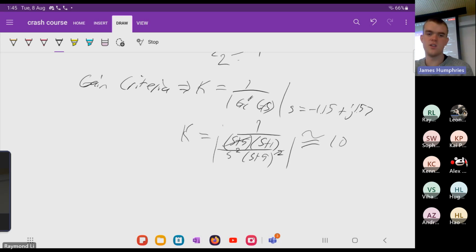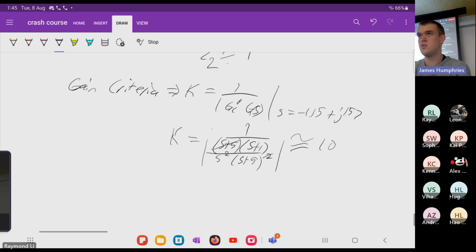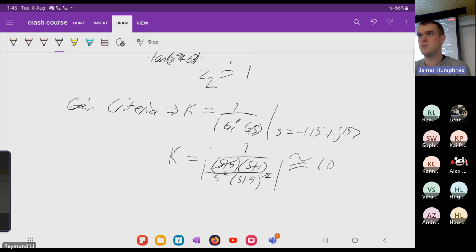Okay, perfect. So you chose where to place the 0 just to cancel the whole, right? Yes. And then the other 0 you chose with the angle criteria. Yes. So we had 4 poles, and I wanted my final answer to have 2 poles, and I was able to place 2 zeros wherever I wanted. So I put the first one to cover up exactly where the other pole was, so then I'm only left with 3. Okay. And now the issue is, I could have placed those 2 zeros at the 2 spots to cancel out 2 poles, and I'd be left with only 2 of them.